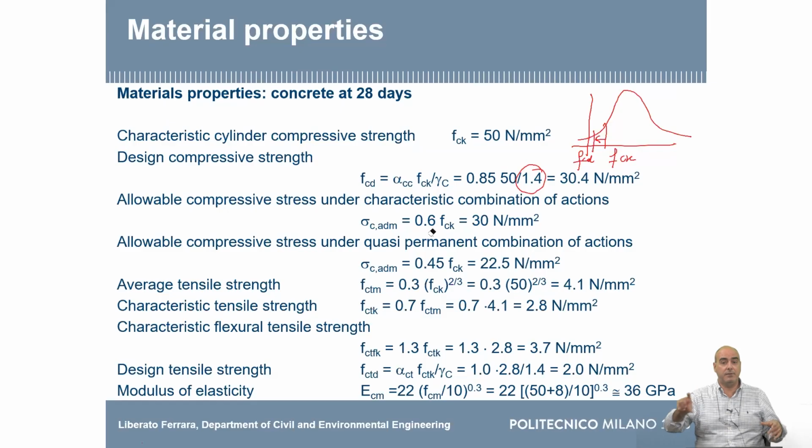But then you have the vehicles. And the traffic load is what we call cyclic. It goes on and it changes. But there is an average value of that traffic load, which we can assume stays there forever. So that is what we use in the design situation.